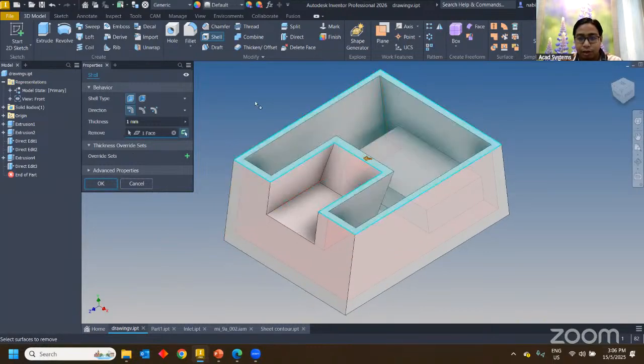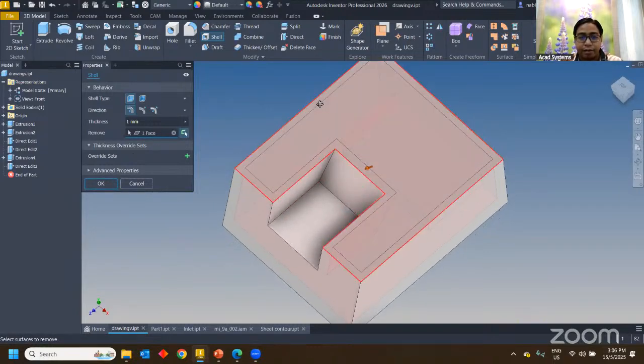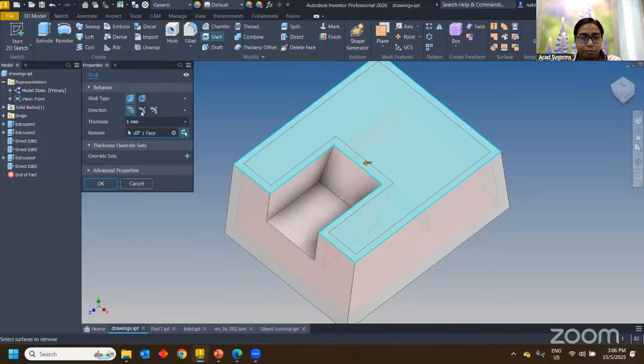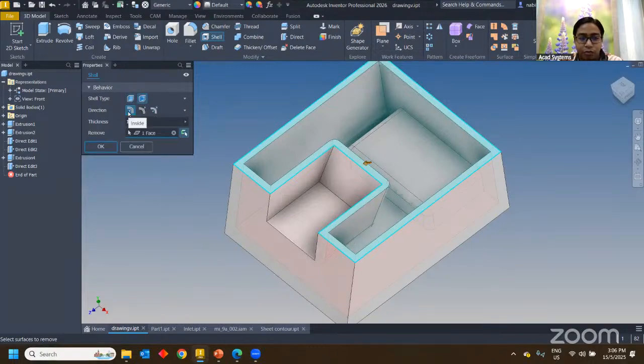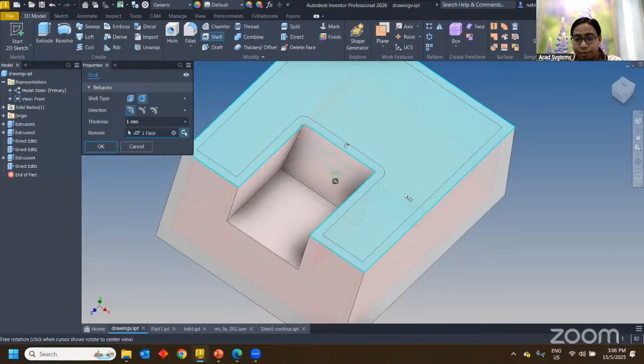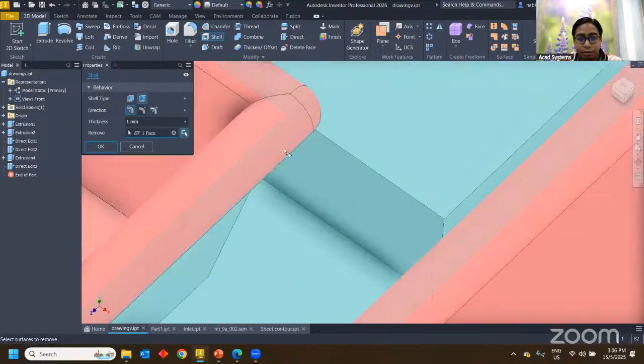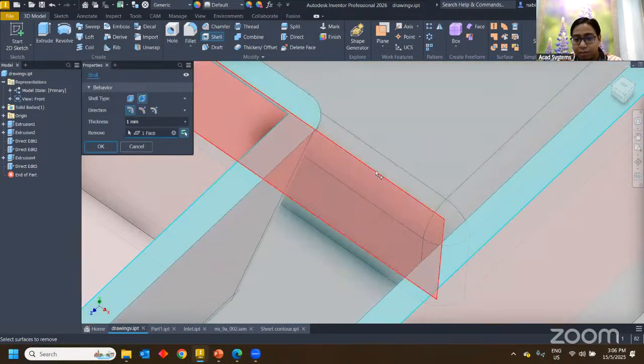When I click here, I can specify if I would like to have a rounded corner, so some of the sharp edges here will be rounded. If I click rounded corner, currently I pick using inside, so it will try to find the inside that can be rounded. And what we see here is these examples right over here. You can see this become inside.